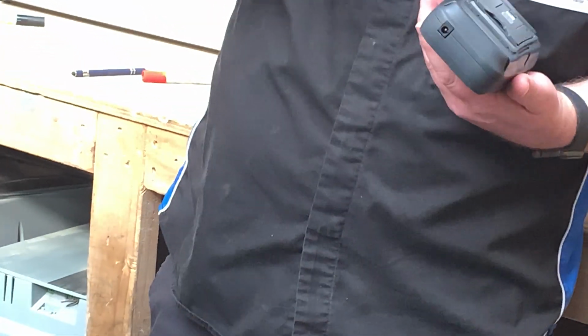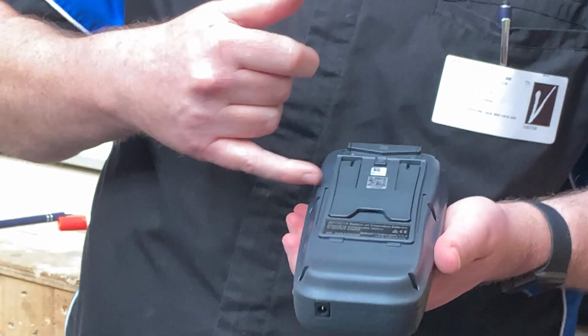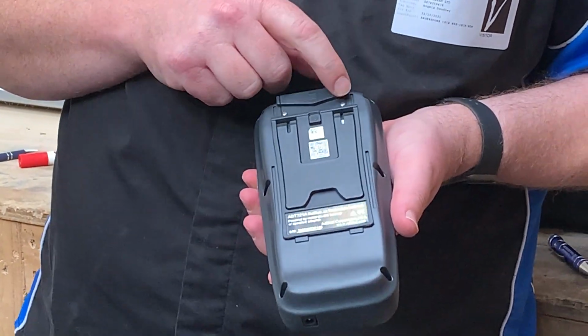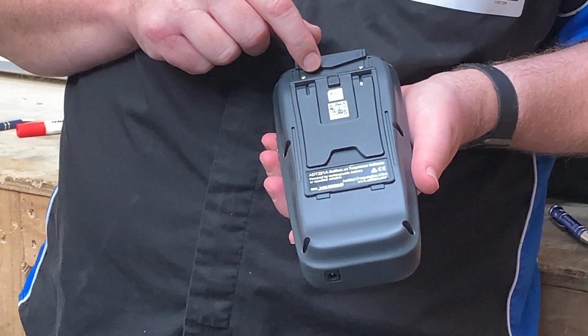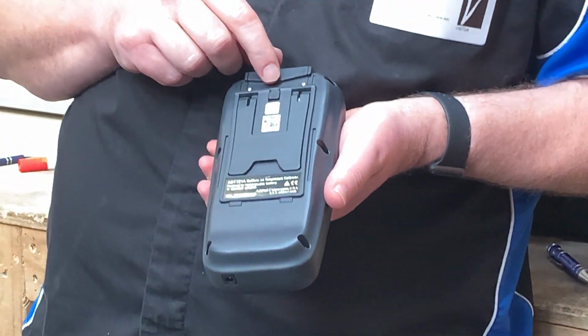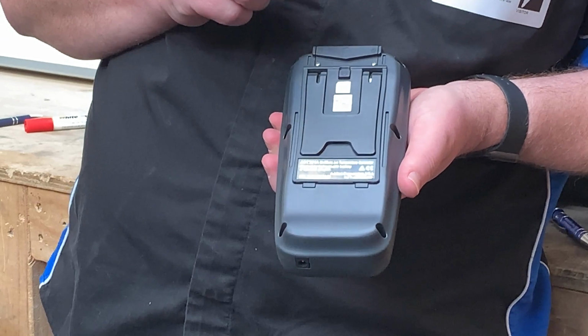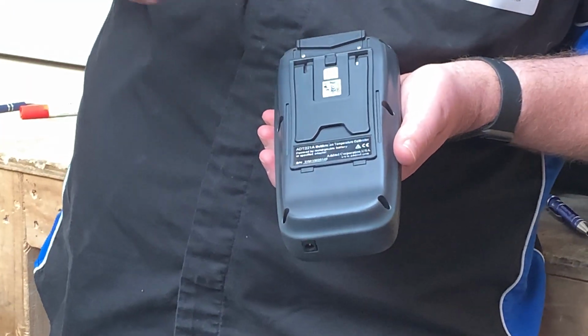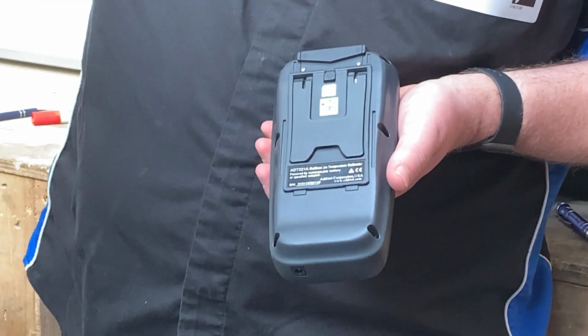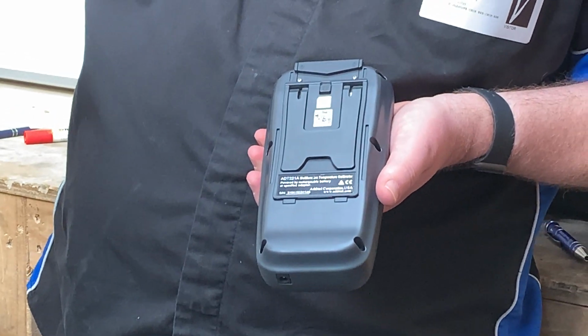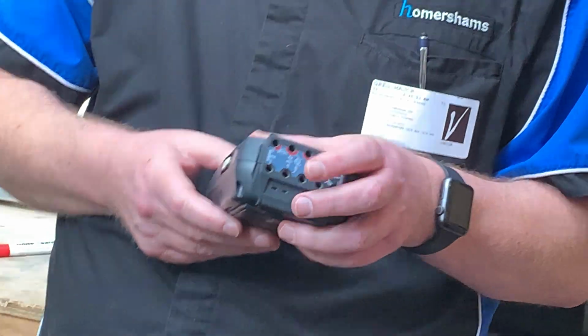So you just charge it by plugging into the power. The built-in PRT sensor is there if you want to do your own ice point. So in theory, in 12 months' time, you might want to bring it back and we'll send it to America to get calibrated. Most people are not going to. You can do an ice point: take out the PRT, which is on a long lead, put it into an ice slurry, and set your 0 point for the temperature, if you want to do your own cal.